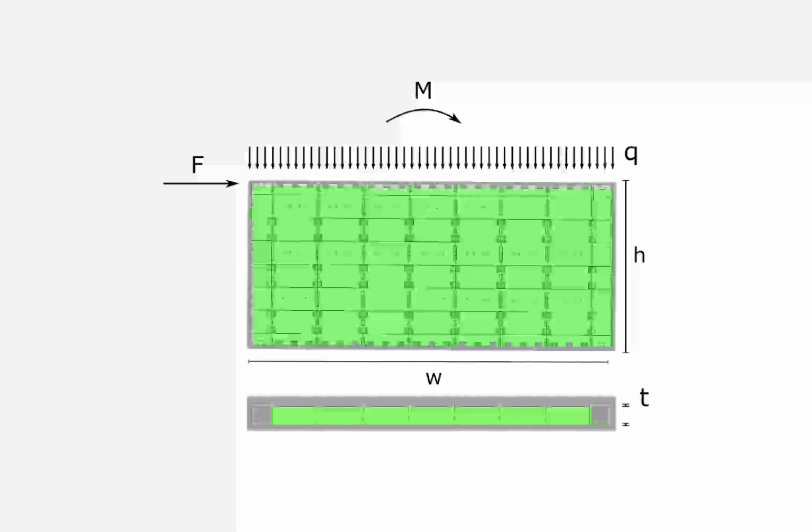So first of all, let's have a look at the structural system resisting lateral loads in WikiHouse. The system that we use to resist lateral loads is shear walls. Essentially, when we join our columns together by using bow ties, they form a shear wall, and we take advantage of the shear wall to take any horizontal load acting on our structure.